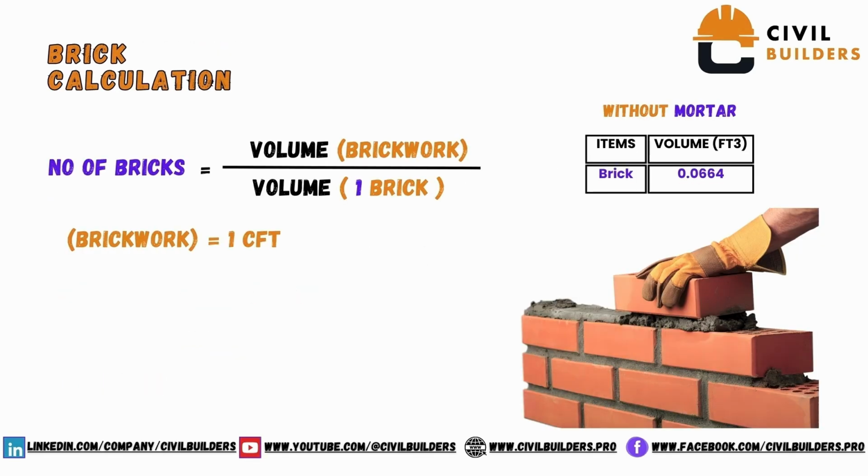Let's calculate the brickwork quantity in 1 cubic feet. We have to use the formula listed above. By inputting these values, we get an answer of 15. That shows us that there are 15 bricks in 1 cubic feet.